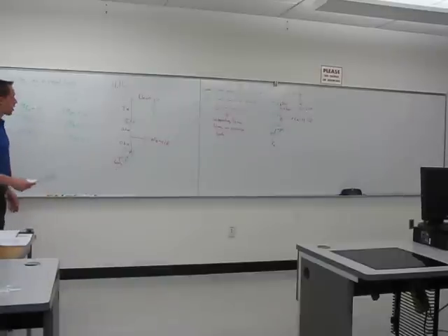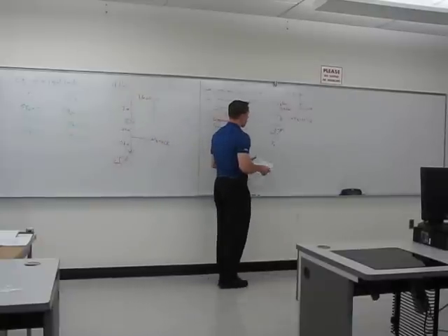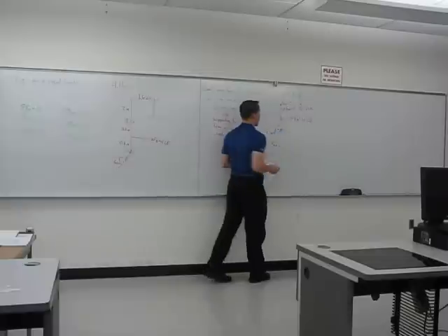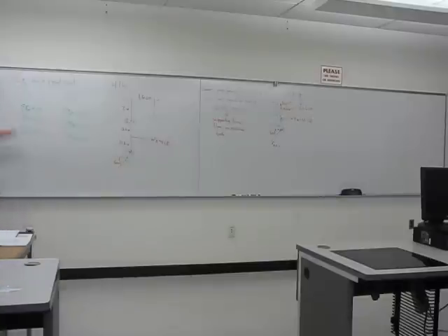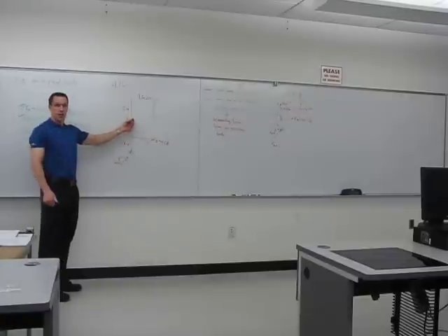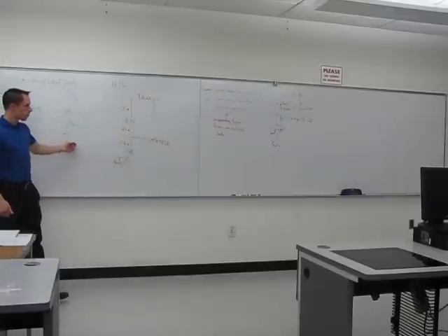Okay, so let's see here. We need to solve for three things: FA, FCX, and FCY. So three unknowns. Like I said, in a two-dimensional problem, you could have three equations with three unknowns. You could have this equation, and this equation. Because if that rigid body were to rotate, the axis of rotation would be the z-axis coming right out towards you. So if we want no rotation, that means that the moment around the z-axis better be 0.